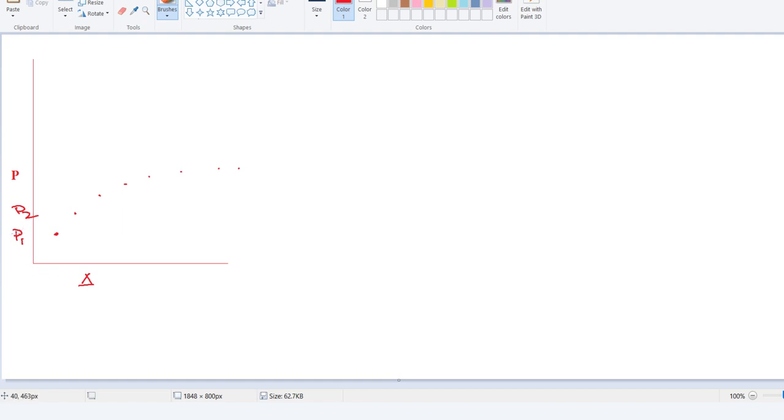Now, if you keep on adding the loads, like the one that we have just worked upon was a load P, or you can just mark it as P1. You have incremented that load, you have added more load on that, and the response was like this. In all the responses, yes, it was converging, but the displacement was getting immensely high. But at a certain point of time, this displacement is no longer a finite value, it's an infinite value. That means the solution is diverging.